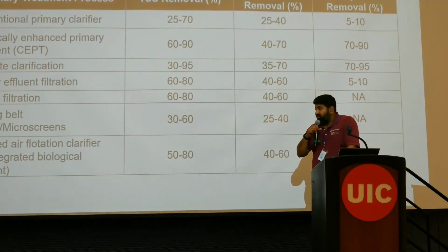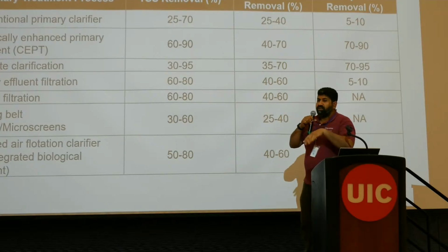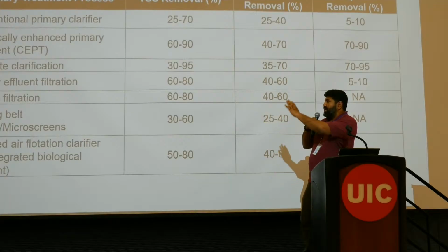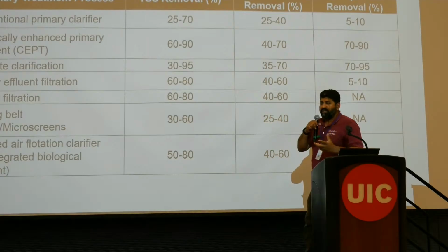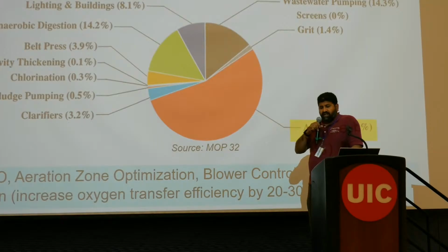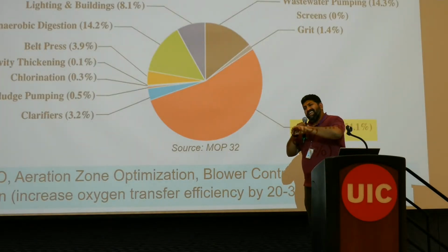Just to give a takeaway point, on primary treatment, the main advantage is you are able to remove the solids and BOD with minimum energy input, and you are also able to remove phosphorus, which is a limiting agent. Energy is another element where, in the US, there is a disparity in terms of where energy costs are, Midwest versus East Coast versus West.